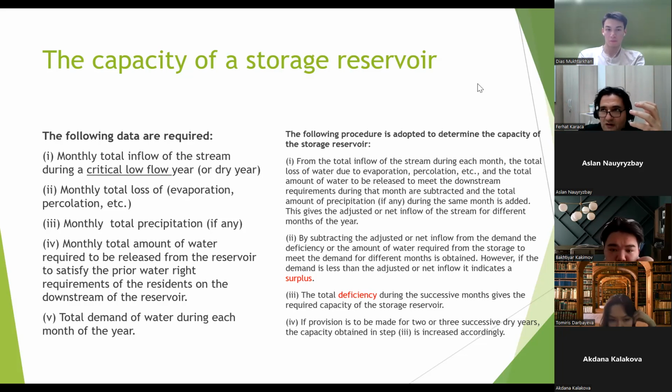For example, if on Fridays the city is cutting water for 5 hours, then you can simply estimate that the reservoir is going to compensate 5 hours of consumption on Fridays. So basically the logic is this: we are designing reservoirs to compensate for dry periods.